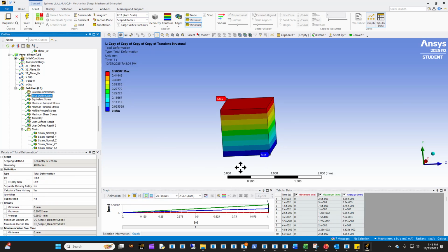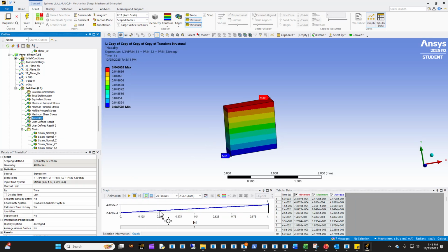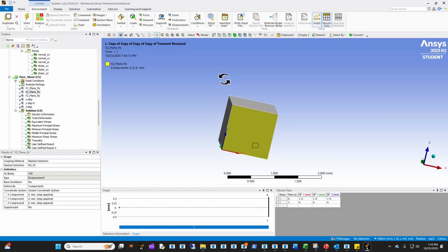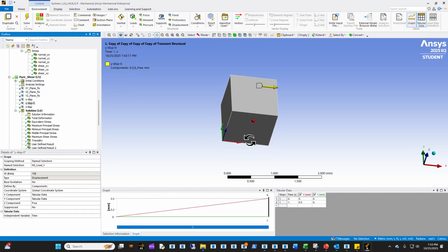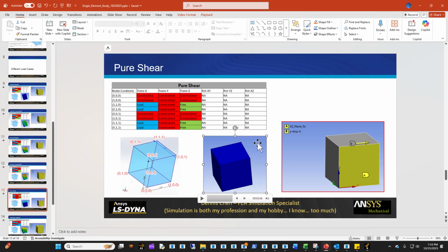Maybe that's not good. This is a better view. Yeah, sorry. There we go. Right. So you're going to be able to say you have a triaxiality of 0. This is how you know you have the correct pure shear condition, and all you have to do is fix the bottom surface and then allow the top surface to go. You're also constraining any outer plane, so you have a pure planar shear across that top surface, and that's how you do it in the single element study.